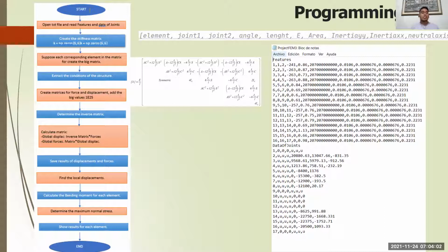It calculates the local K matrix for each element. Having done this for each element, the next step is to build the global K matrix. The second part is boundary condition and stress calculation. Now the program solves it as learned in class, and the vectors of force and displacement are filled with the results.